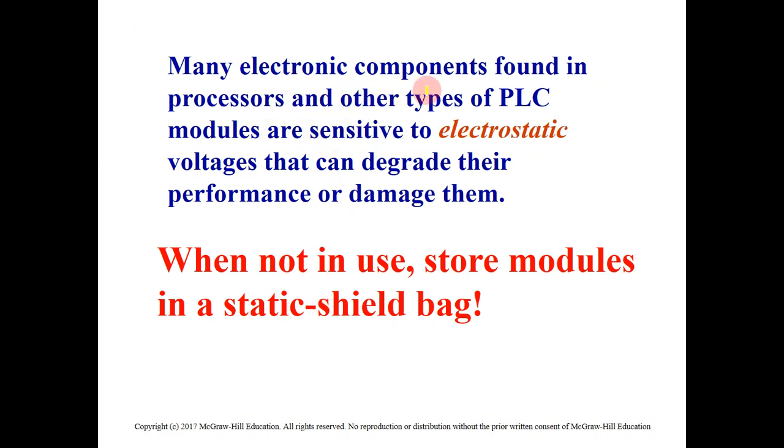Many electronic components found in the processor modules here, or other types of PLC modules, are sensitive to electrostatics. So if we do not use these modules or components, we need to keep them in a static shield bag, to avoid damage to the electronic devices by electrostatic charge.